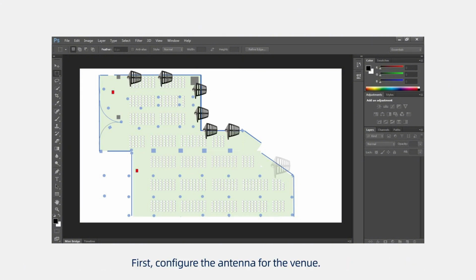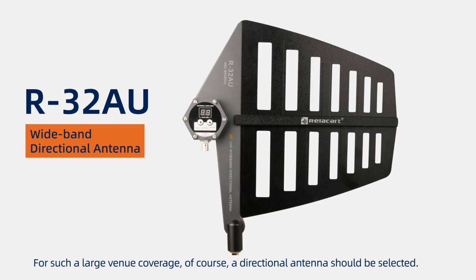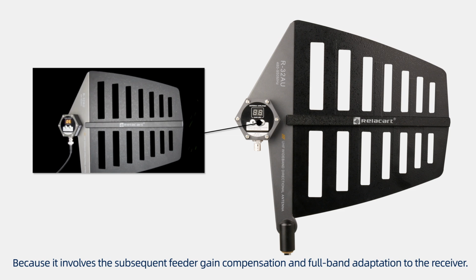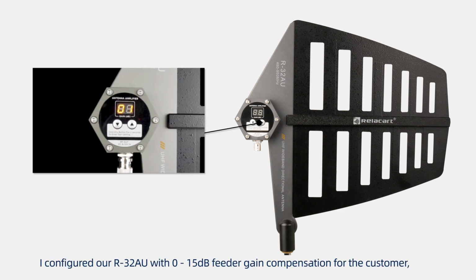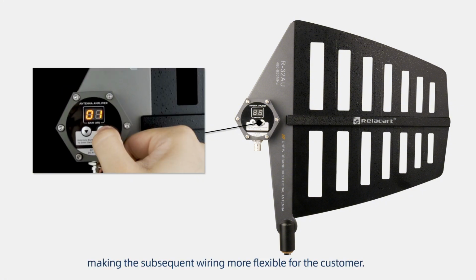First, configure the antenna for the venue. For such a large venue coverage, of course, a directional antenna should be selected. Because it involves the subsequent feeder gain compensation and full band adaptation to the receiver, I configured RL32AU with 0 to 15 dB feeder gain compensation for the customer, making the subsequent wiring more flexible for the customer.